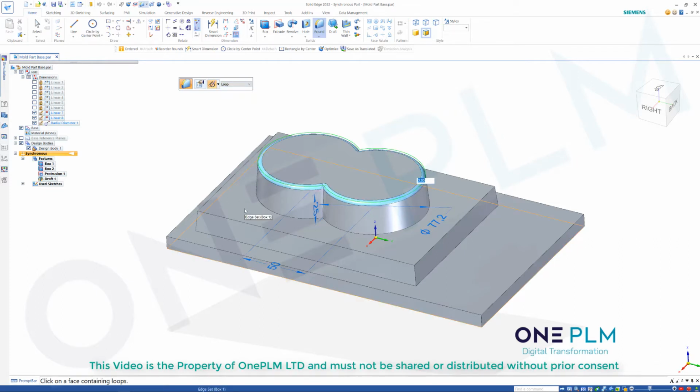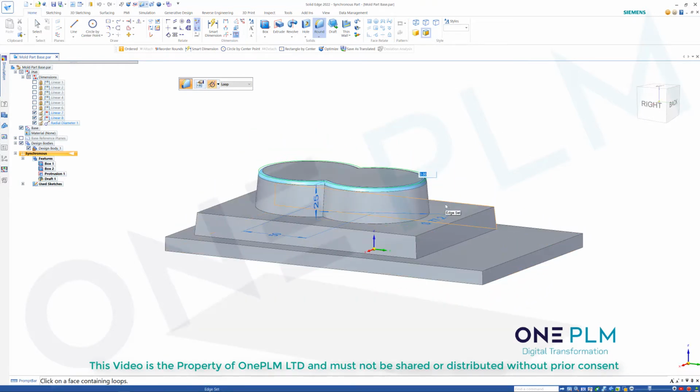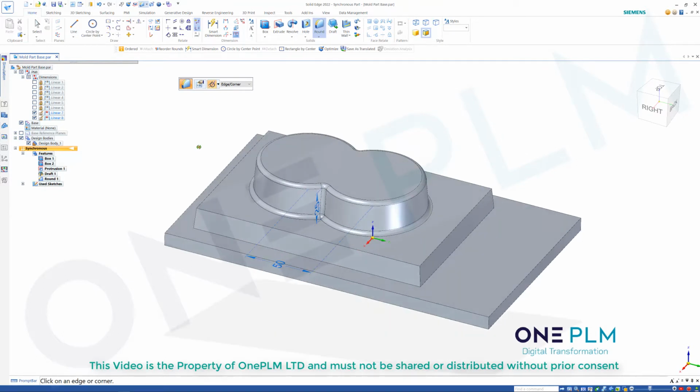Then I'm going to change and do a loop. A loop is the inside or outside edge of a face. Just be aware that's obviously picking up that face. By spinning that rotation or using quick pick, it's allowing me to select that plane, and then that loop, which is the inner loop that we've got. Then add the edges that we want to finish this profile off, and right click to finish. So we've got our round down there. We can then do the rest of these.